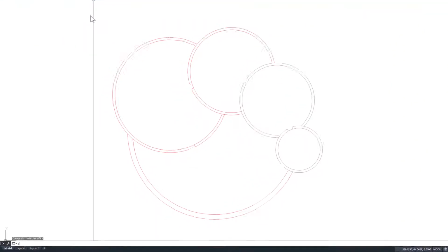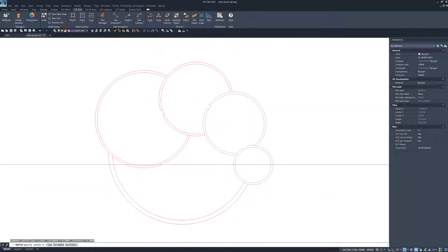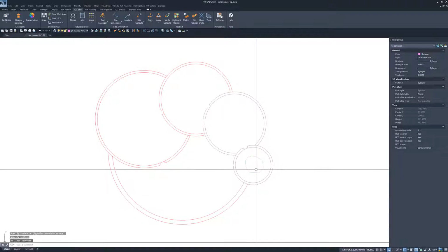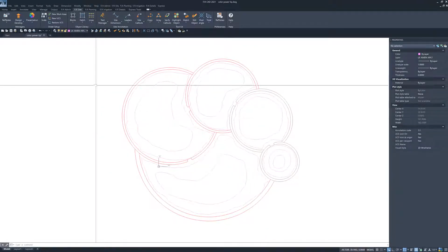We will use the sketch command to begin drawing our color hatch outlines. The goal is to create regions that will represent deeper and darker colored water versus more shallow and lighter colored water. Doing this freehand with the sketch command will produce a more organic look than using commands such as offset or simple circles. Now that we have our non-plot polylines in place, we can set up our colors.